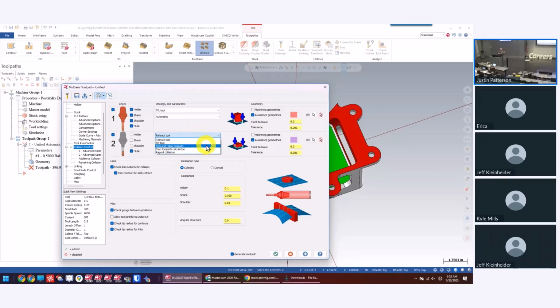Trim and relink a toolpath, what it does is whatever the collision it sees, it literally cuts the toolpath off right there. And then it has to relink it, right? It doesn't do anything but cut it all off. It's like using a pair of scissors. Where a retract tool, especially in cut center, says I'm going to avoid that. Instead of cutting it, I'm just going to move it back in and move it back to the cut center. See what I'm saying? So this is where we can do a lot with this.